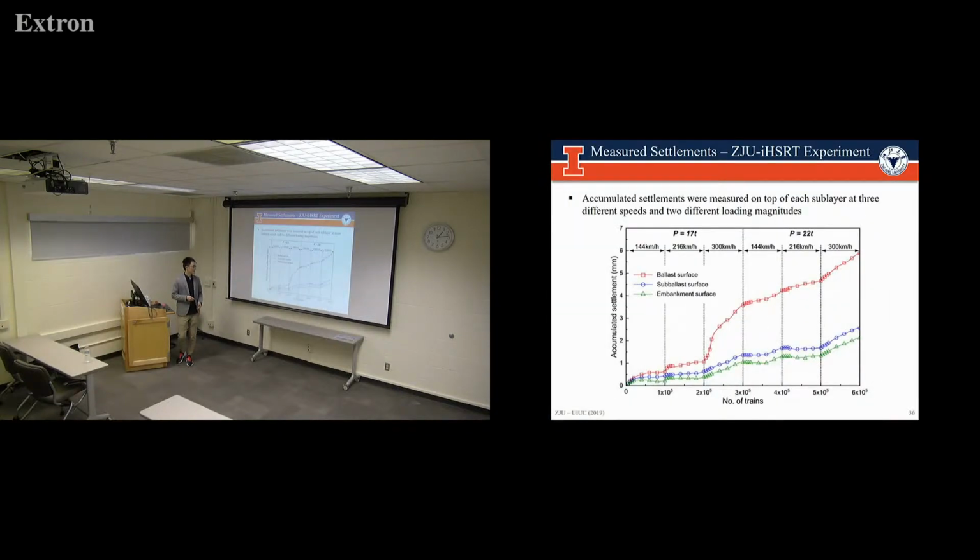Yeah, so we can see from here, as you mentioned, the conditions of the ballast. If you take notice here, even though they showed the correct trend in the accumulated sediment, overall the magnitude is only up to 6 millimeters, which is too minor for us to model anything. That's because in the lab, before they did the measurement of the accumulated sediment, they had already put some loading on top of the tie. So the initial settlement that happened in the tie was not recorded.